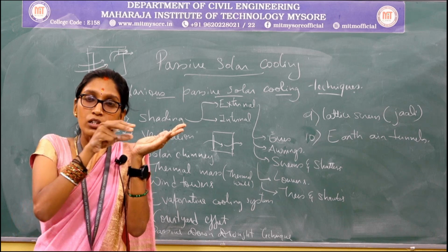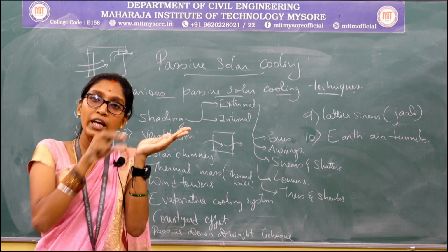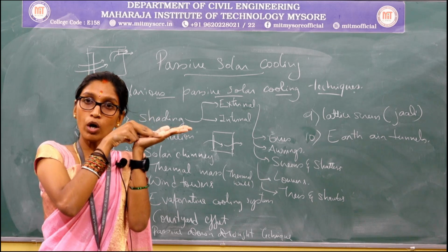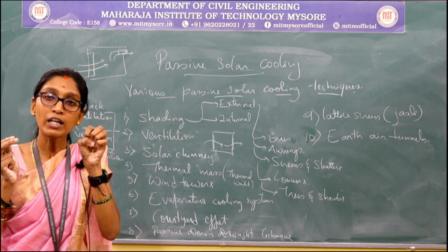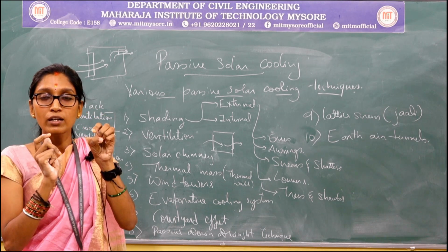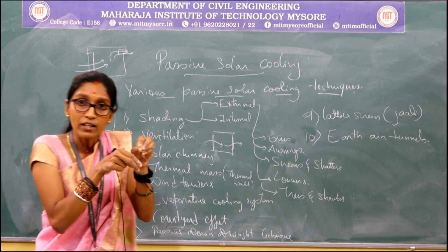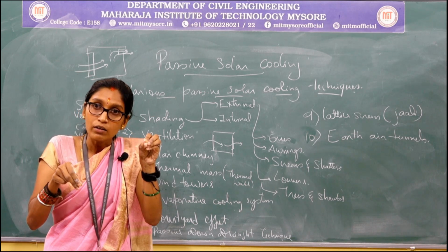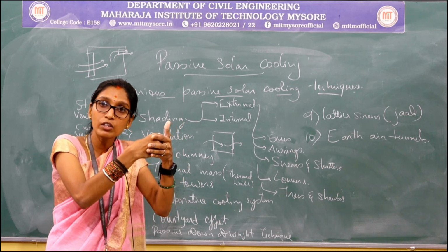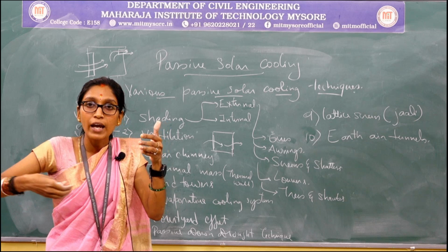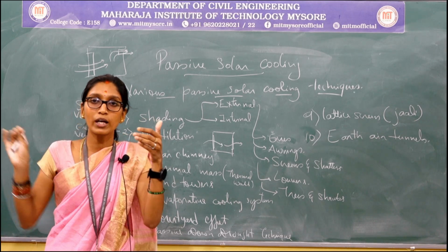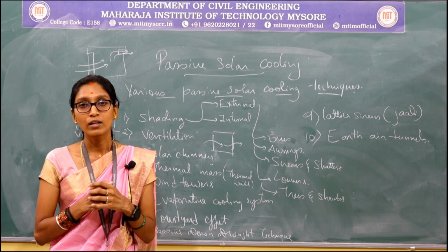So the temperature of the air will go down due to the water molecules present there, and these water molecules, as they gain heat energy from the air, are going to evaporate, right? And the air which has come in contact with the water would have cooled and gained a cooling effect, and that air is moving in a downward direction into a building, right?